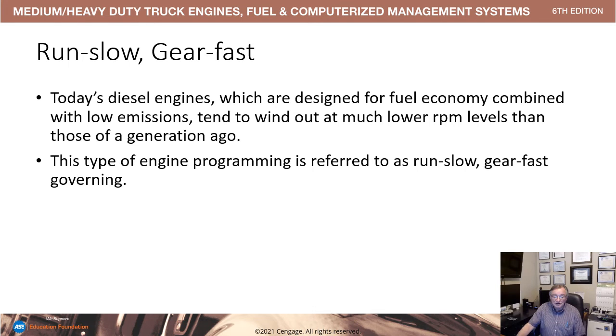Run slow, gear fast. Today's diesel engines, which are designed for fuel economy combined with low emissions, tend to wind out at much lower RPM levels than those a generation ago. This type of engine program is referred to as run slow, gear fast governing.